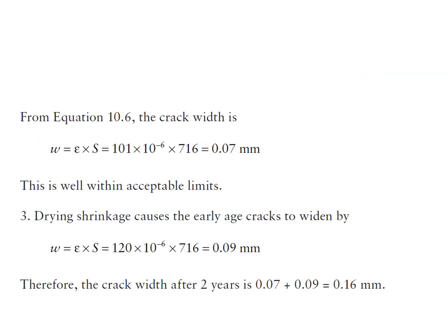Now we can calculate the crack width, which is simply that restrained shrinkage strain multiplied by the crack spacing. So we haven't got much in the way of cracking here. 0.07 millimeter thickness. So that's well within the acceptable limits.